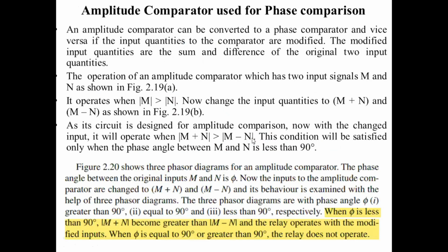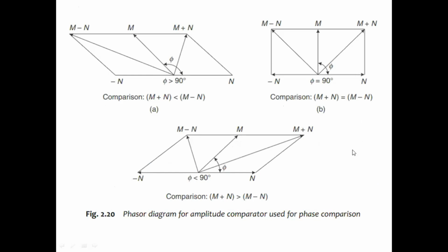Next, in the figure there are three phasor diagrams of the amplitude comparator. This is the phasor representation of the amplitude comparator used for phase comparison.